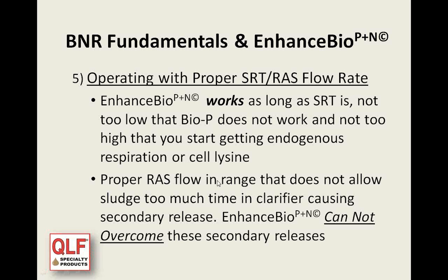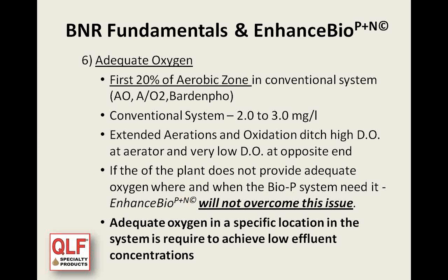But on the RAS part of it, I found a number of treatment plants where their return sludge flow rate was a little bit slow, and they had too much of a sludge blanket. And with that sludge blanket in the final clarifier, it caused secondary release. EnhanceBio will not overcome that. In fact, it will make it worse because now you've got more carbon to release in your final clarifier.